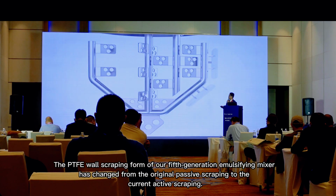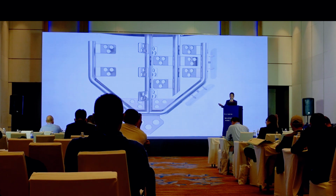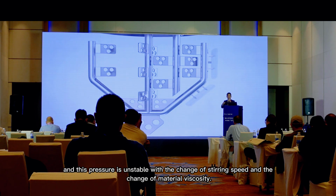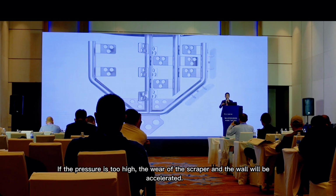The wall scraping form of our 5th generation emulsifying mixer has changed from the original passive scraping to the current active scraping. The scraping force of the passive scraper comes from the pressure of the material body on the scraper during stirring. And this pressure is unstable with the change of stirring speed and the change of material viscosity. When the pressure is insufficient, effective scraping will not be formed. If the pressure is too high, the wear of the scraper and the wall will be accelerated.